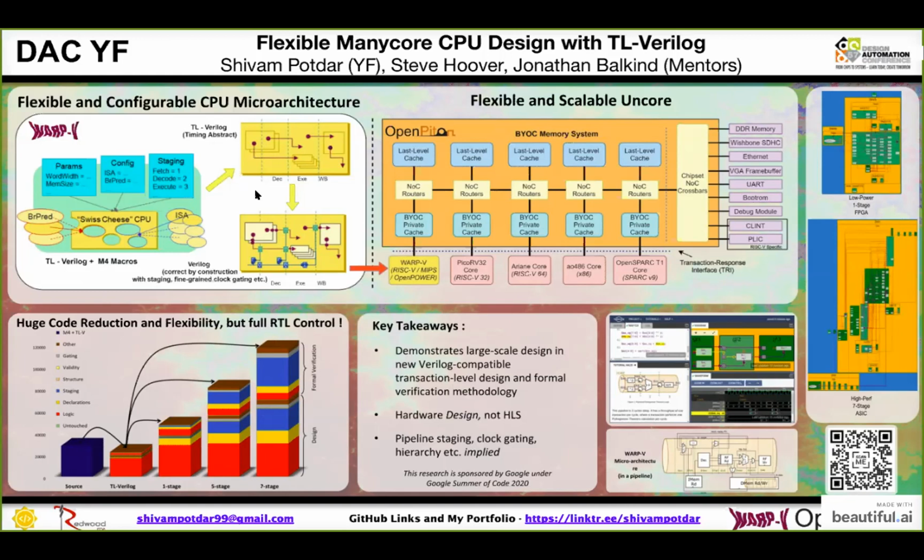And on the other side, we have the system called OpenPiton, which is made by Princeton University and is also open source, which is a framework apart from the CPU core itself. It is a base framework for multi-core systems. So when you build a quad core processor or something of that sort, apart from just the cores, it needs a lot of other technical parts, which is cache coherence. Then you have interface with external components such as memory and etc. So all that requires a good amount of hardware, which has to be multifunctional.